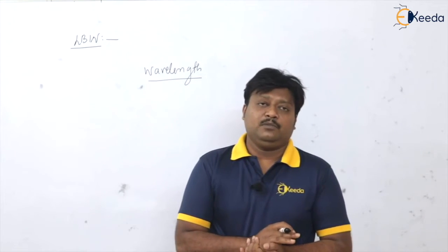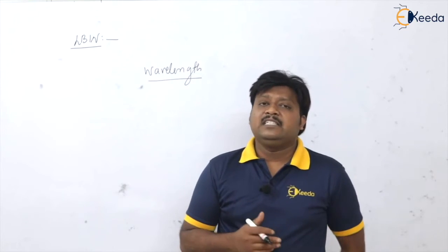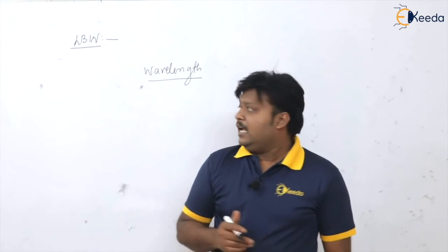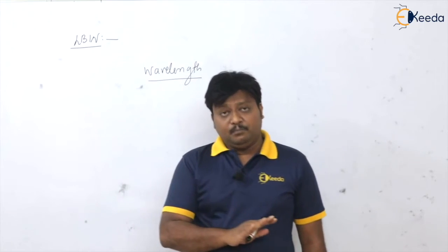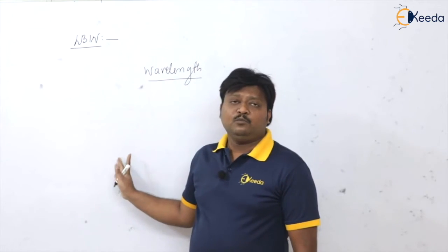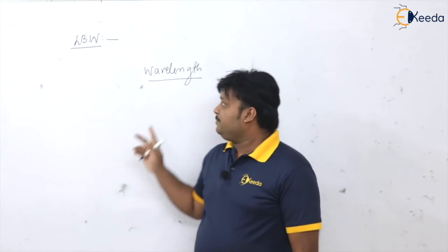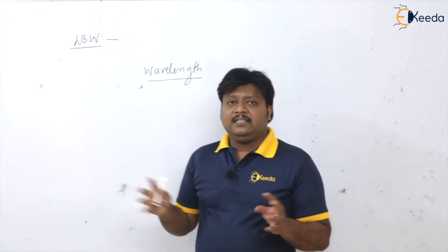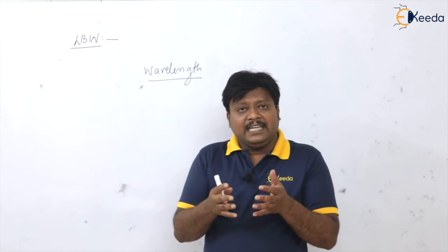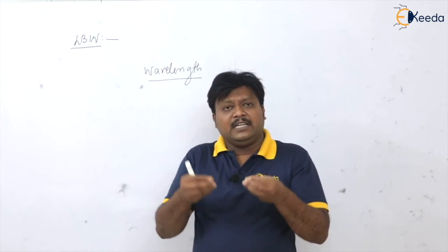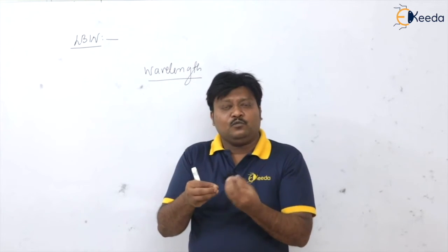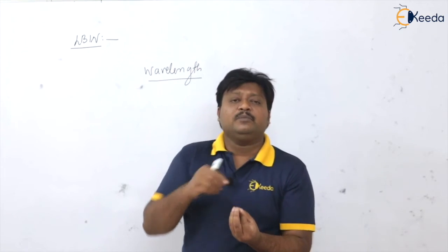This becomes the laser welding process. The major advantage compared to EBM is that no vacuum is required. Also, the weld area is very small, up to a few microns in diameter where the laser focuses on the workpiece.